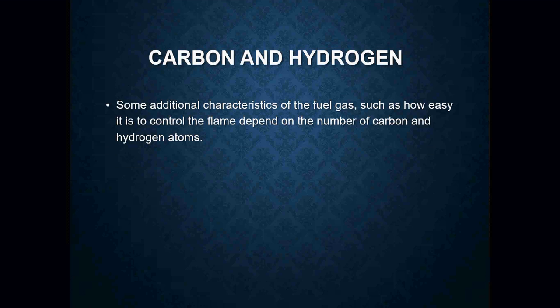So when we are thinking about a natural gas furnace versus maybe a propane heater, I have to be able to regulate a certain amount of gas to my burner so that I don't create an undue explosion because I'm just introducing way too much gas to air and spark ratio. I have to be able to control that. The only way I'm able to control that is through my gas pressure and through the orifices of that appliance.